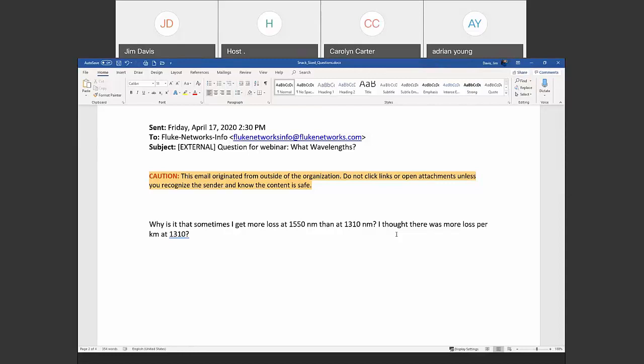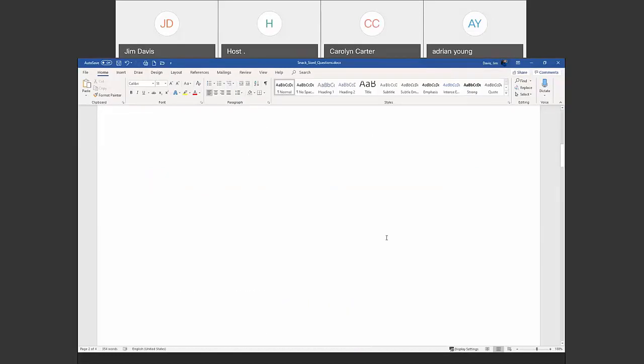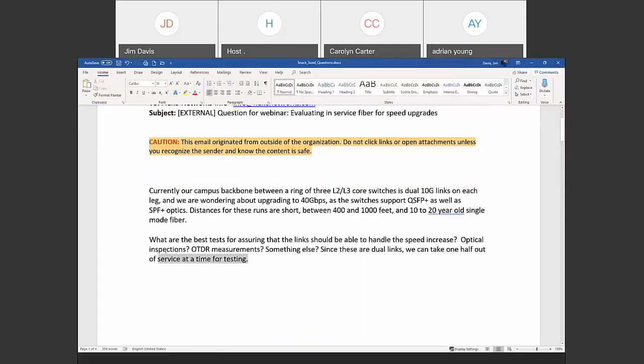And we missed a second part on that question, if you can go back up there, Jim. So there was a question on there. It's like, well, what is the best thing to use to figure this out? Given that it's a 20-year-old fiber, this is a personal preference. I would rather turn to an OTDR. Typically, I would use an optical lens, and yes, we would do inspections. But that fiber is 20 years old. I want to make sure that nothing untoward has happened to that fiber, and that OTDR will actually allow me to look down that fiber cable and see if something has happened to it in the past 20 years. Who knows what adds and changes and questionable rerouting of cable has actually gone on during that process.